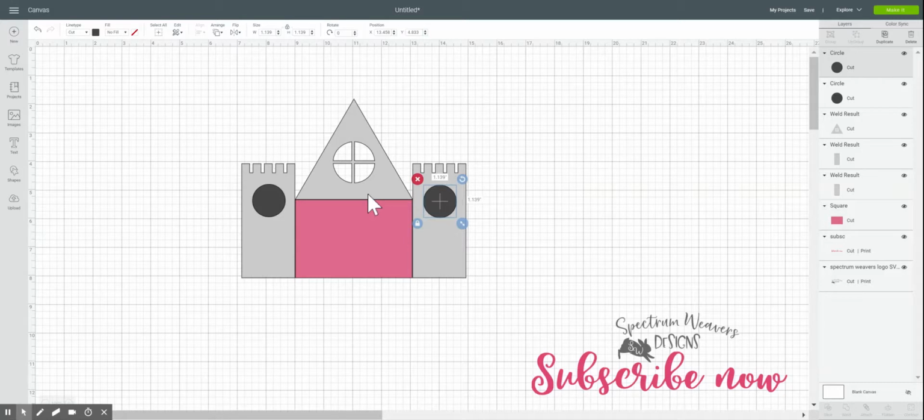But just for the sake of showing you how each of the different features of Design Space works, I'm going to show you this. So with that selected, again, press Control, and then click on this other circle. Okay, and now I want to align and align vertically, and that puts them both so that they're exactly vertical to each other.